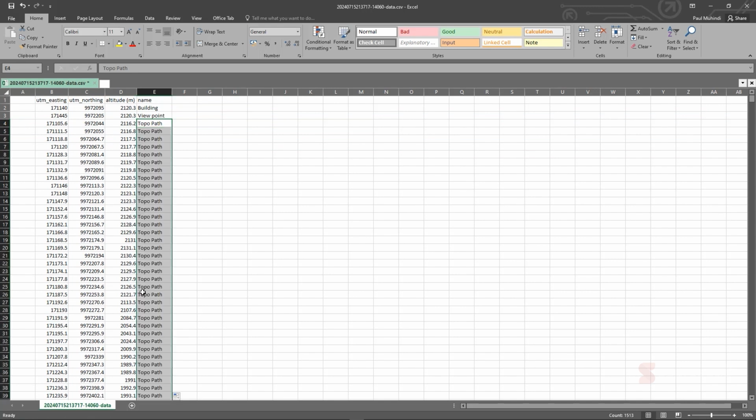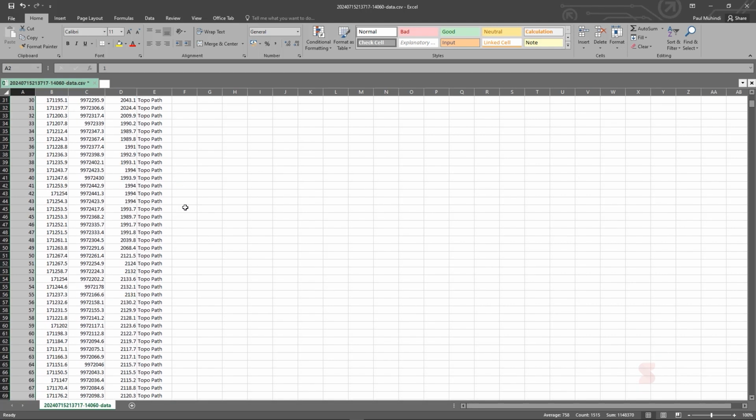This topo map, I remember it's all of them. So I'll double click to propagate all the empty cells with the same information and just add these two items. Under here, I'll name it as number, but we'll delete this row before we take it to our Civil 3D, because it will be given as an error. This is description just for now so that you can understand. And under number, we can now select 1, 2, and then once you have these two, you can double click to propagate the rest.